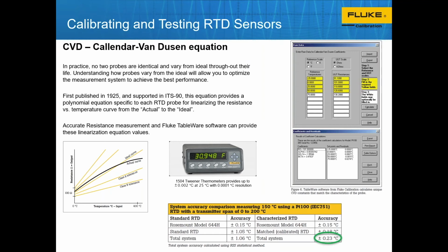And if your secondary probe can give you either the actual resistance value with enough accuracy or the Fahrenheit value with enough accuracy, you can get some pretty significant improvements in the accuracy of the dry well itself versus the sensor that's built in board to control the temperature and do the set point. So this case here could be, easily 10 to 20, 30 times more accurate than the accuracy of the dry well itself.